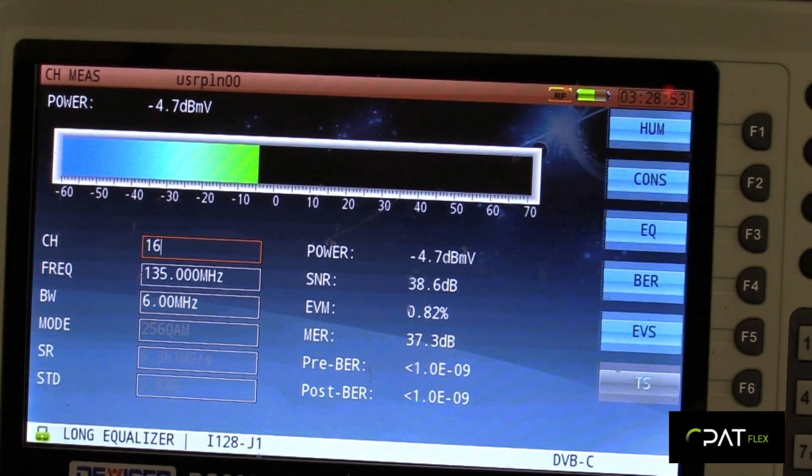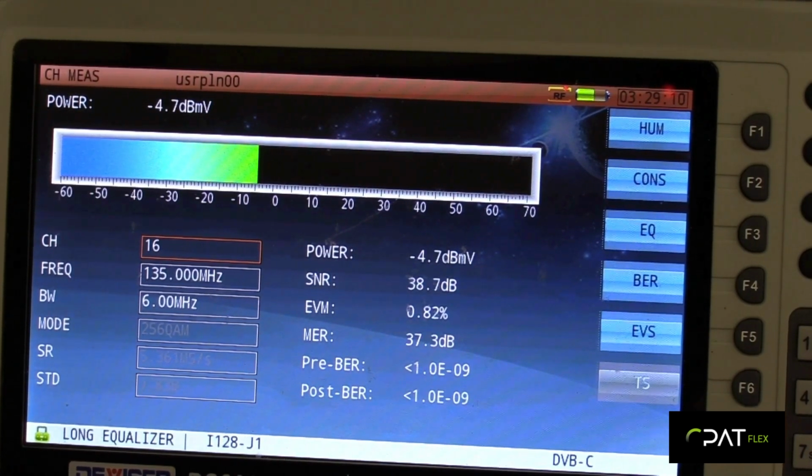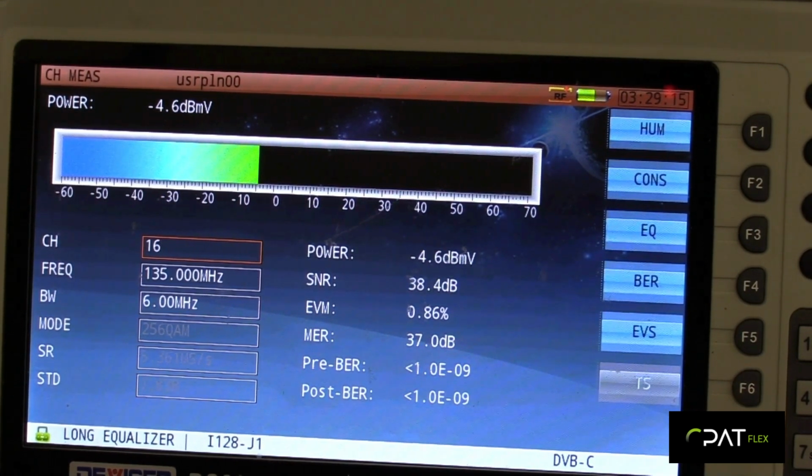In order to make a proper measurement, you will need to find a test point after the downstream combining so you can measure the QAM channels together with the injected DSG1 frequencies. You will need to make sure you have enough level at the test point to make a valid MER measurement of that QAM channel. Typically, you should have at least a -5 dBmV signal for a 256 QAM channel.